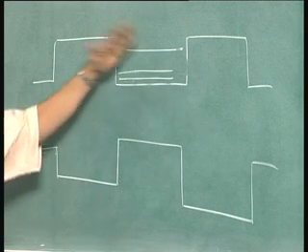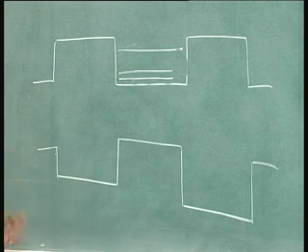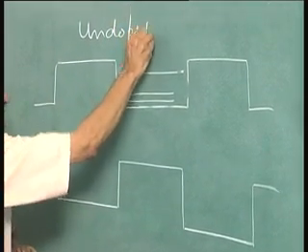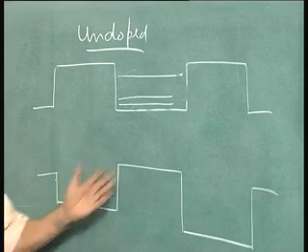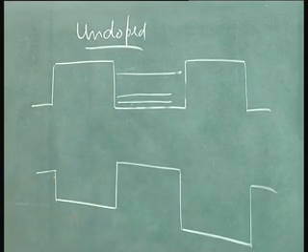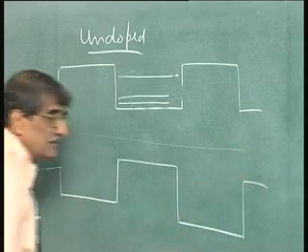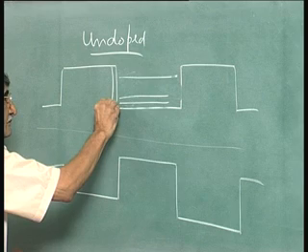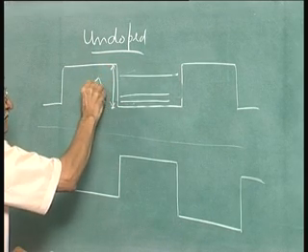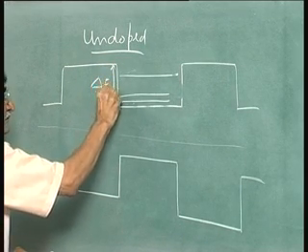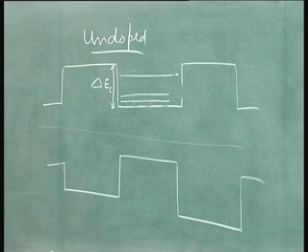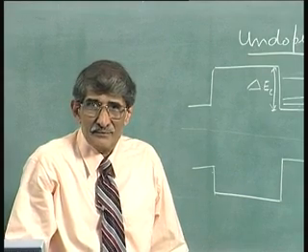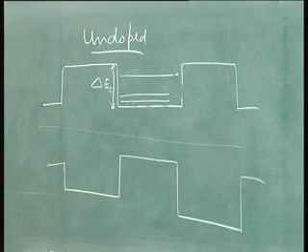So, what I am trying to point out here is undoped. I have put down there, wide band, narrow band gap, and there is no potential change. Okay. All that you will have will be intrinsic level going down like that, coinciding the Fermi level, and you have that a delta E c there. This is only for illustration I have put. Nobody will be having any fun in making heterojunctions with undoped materials. Okay. So, whenever you do, you will have doped materials. In fact, we have discussed that in the last presentation.